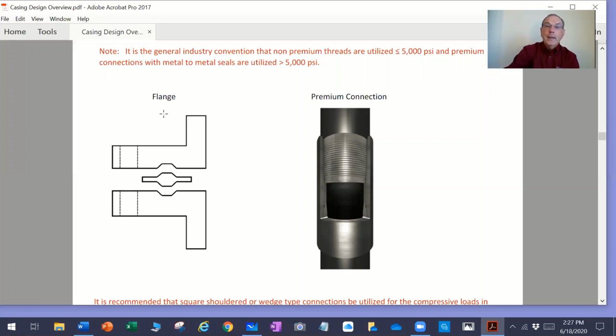If we've created 60,000 PSI stress on this face, and it's going to be operating at 15,000 PSI, 15,000 PSI will not leak past 60,000 PSI. That's the way it works. We've created a stress greater than the pressure that we're going to be operating at, which is 15,000 PSI. Therefore, it's not going to leak.